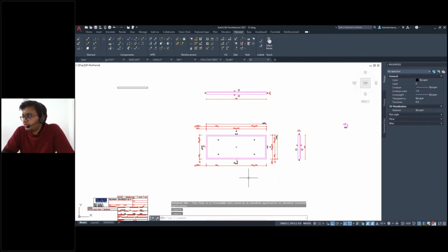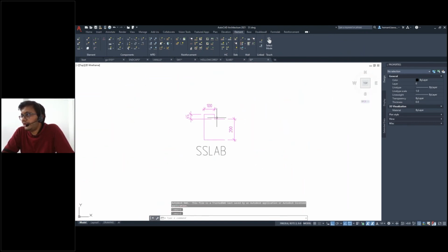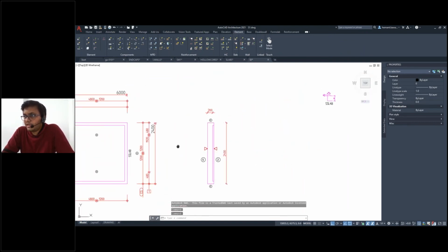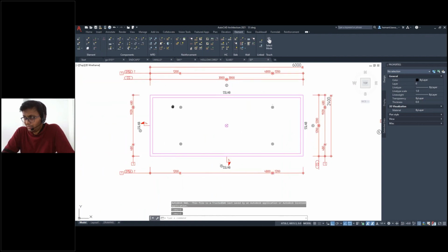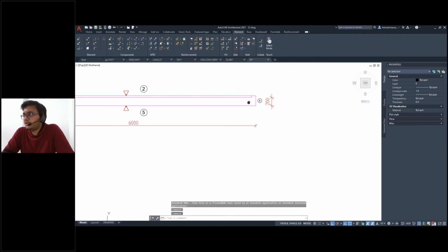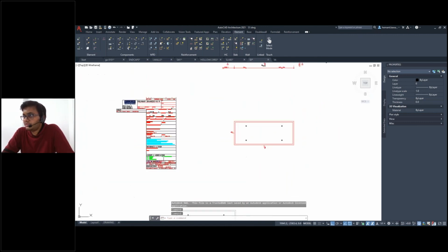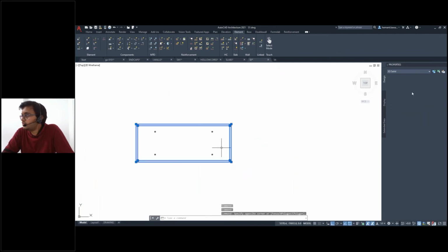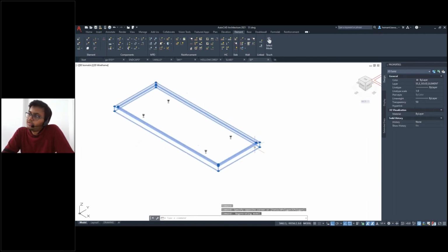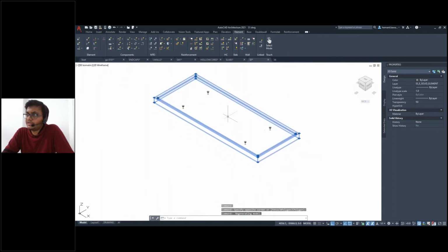So you can see this extra geometry, the height that we defined in the end cap, 45, is added in this whole slab. Even though the main thickness of the slab is 200, this extra geometry is added to the end caps. And if we quickly look at the solid, this geometry can be useful for inserting or casting the handles on the side of the balconies.